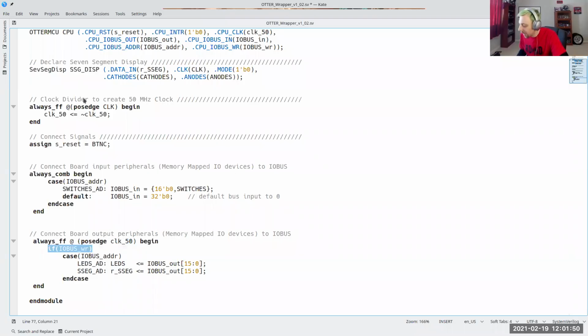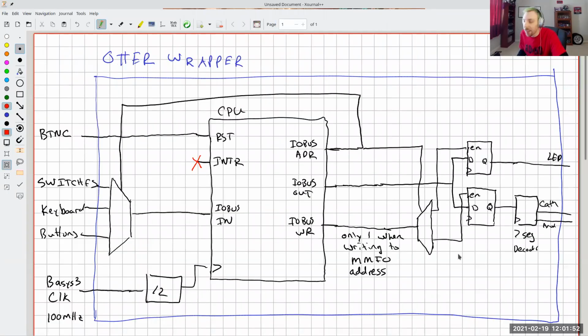Yeah. So if this signal isn't a 1, then I don't need to mess with any of these, right? They can all stay whatever they are. So I only need to think about changing these if this thing is a 1. So if this isn't a 1, leave everything alone. But if this thing is a 1, then I've got to update these registers, right?